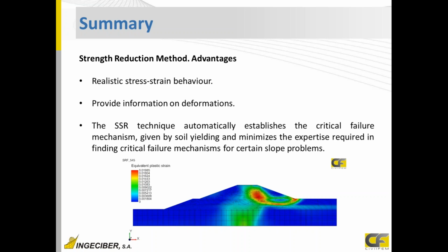Well, just like a summary of this, of one of the first geotechnical material models that we are seeing in these webinars, is the strength reduction method for slope instability that can give us much more information of the model using the CivilFEM nonlinearities. Also, we can mix these nonlinearities with code design by code and any other configuration.